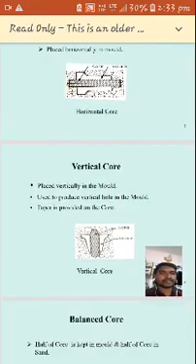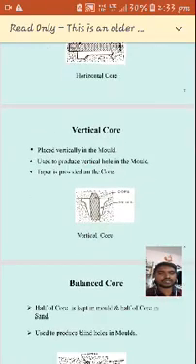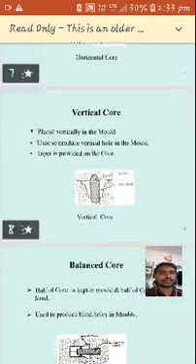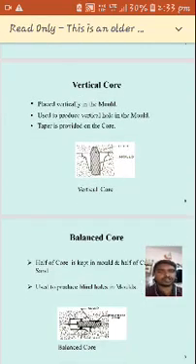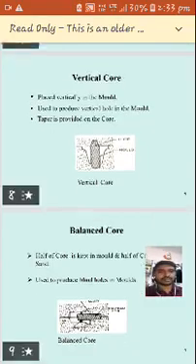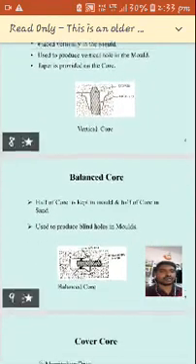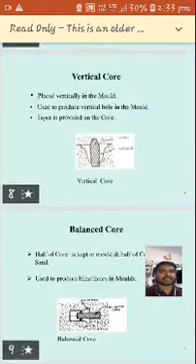Same as the vertical core, it is placed vertically in the mold, used to produce vertical holes in the mold. A taper is provided on the core. That is about the vertical core.